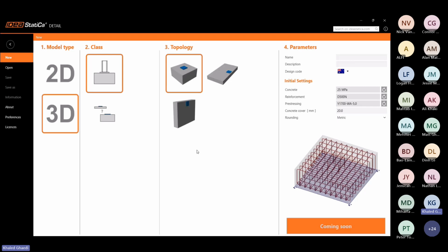You can edit everything again here just by selecting the component. Since we have the base plate, we have the compression only spring, and you have the information about the base plate. Here you have different methods to transfer the shear force from the base plate to concrete. For example, you have the shear lug, and again everything is editable. I can just play with the parameters that I have here. I want to put the shear lug exactly at the center of the base plate. I put it here, and you can rotate it. For example, I can rotate it by any angle that I want.